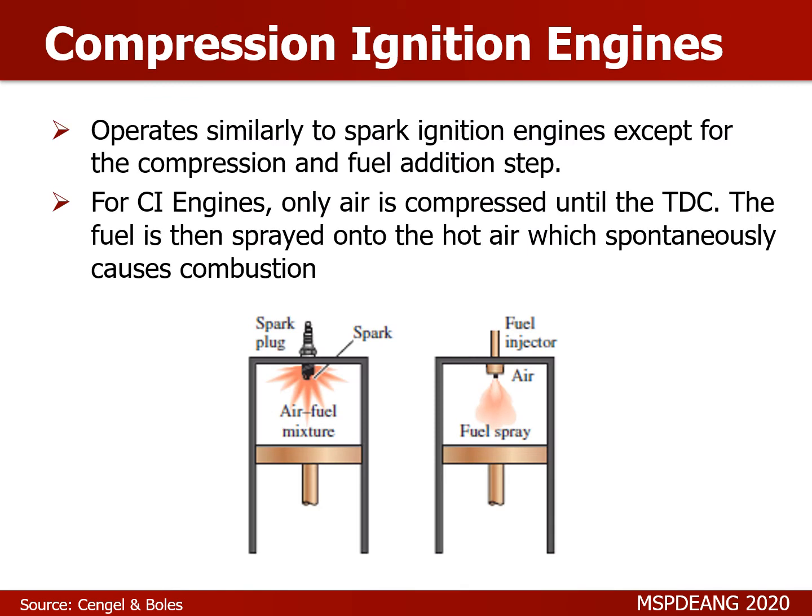Okay? So another type of ignition engines are known as your compression ignition engines. And the compression ignition engines operate similarly to spark ignition engines except for the compression and the fuel addition step. For your compression ignition engines, only air is compressed until the TDC, and once you reach the smallest volume, the fuel is now sprayed into the hot air mixture.